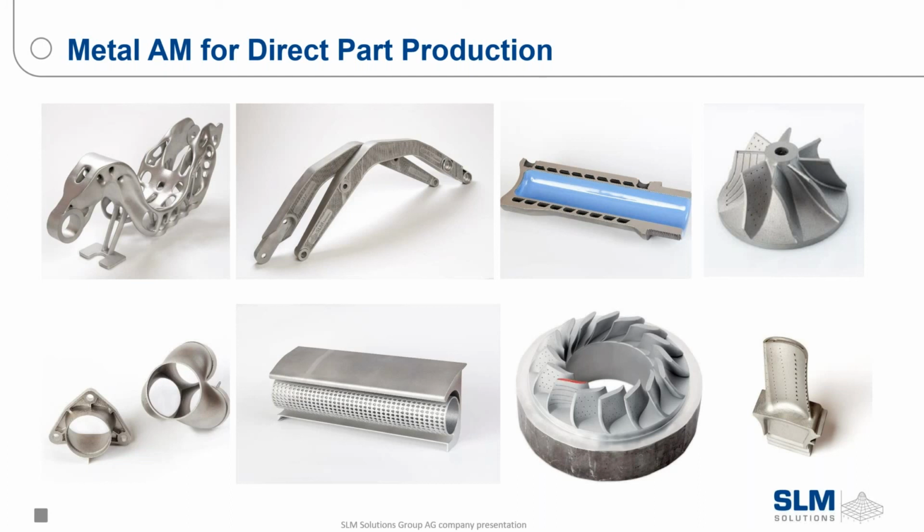Size limitations. Is the 280 millimeter square the largest part that can be made at this point? No, the SLM 500 is 500 millimeters deep, 280 millimeters wide, and 365 millimeters in Z height. But we have announced that there is going to be a square machine in the next handful of years. I know a couple other competitors already have them, but we're producing a square machine, I believe up to 12 to 16 lasers. So it's going to be a big system.